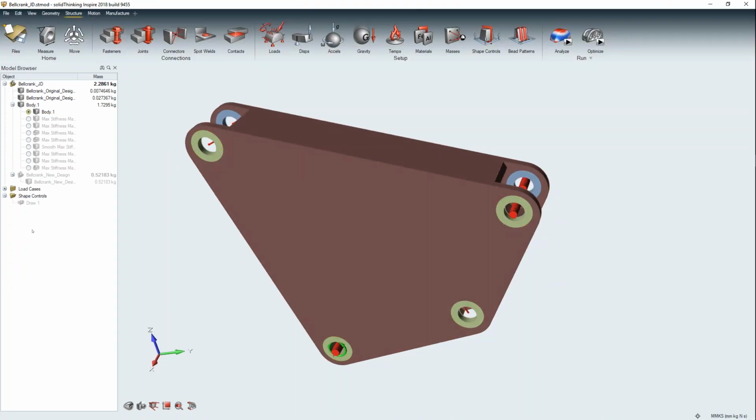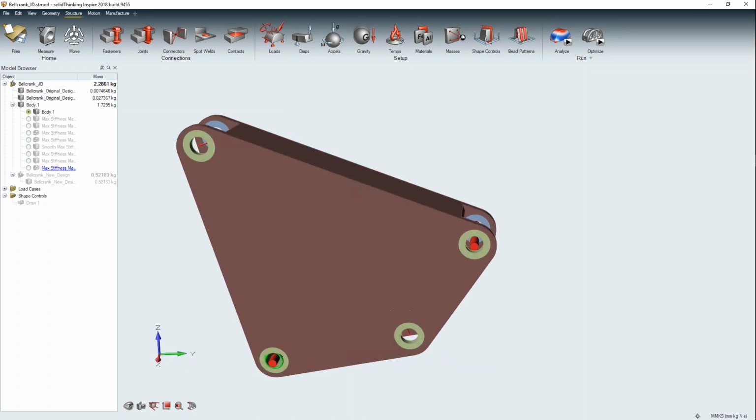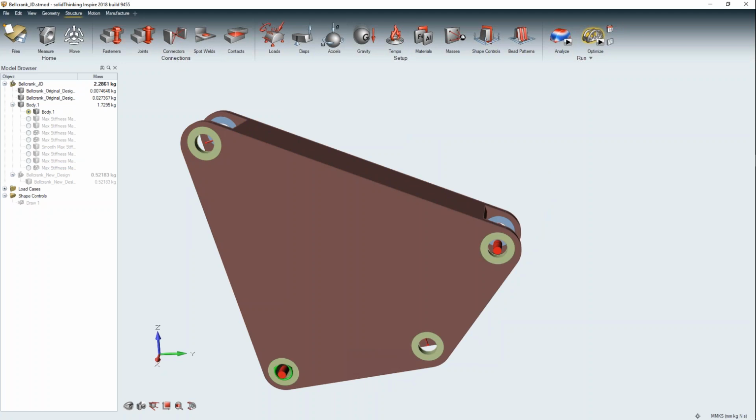So this is the same exact model. I also ran this model for multiple load cases. One load case can be the car just cruising at speed on a real nice smooth road, or the next one is turning at a radius or hard braking. Those can be different load case scenarios, worst case scenarios, and then Inspire comes up with a design for